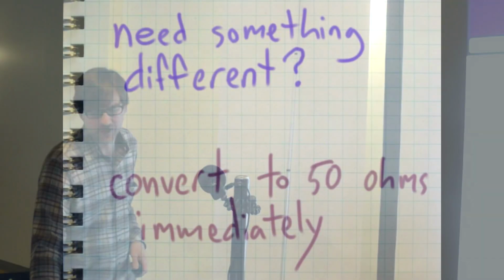So that's it. This is the most complicated part of the talk right here. It's just using this PCB calculator. And you only have to do it one time, because all you're figuring out is how wide you need to make your 50 ohm traces on your circuit board.